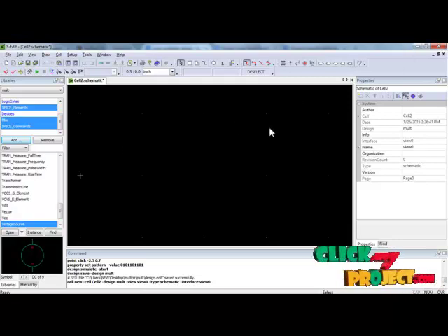We can design the circuit based on CMOS transistors by using SEdit. Before we start the simulation, we have to select a new cell. Here is the cell menu. We select the cell menu and then select new cell. There you can select a number of cells, like cell 0, cell 1, up to cell n.